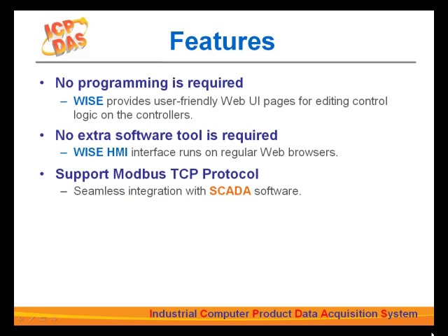All WISE products support Modbus TCP protocol. Most SCADA software supports Modbus TCP protocol, so you can easily get most remote information from the WISE controllers in your control center with SCADA software.